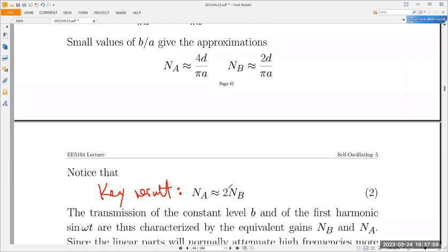Now we break up into, I think you all do engineering. If you have AC signal and DC signal in the circuit, you can do DC analysis and then AC analysis. Have you all done that before? All right, you can break it up into 2 parts. Do AC analysis, DC analysis. Then the result can add back together because of superposition, that kind of thing.